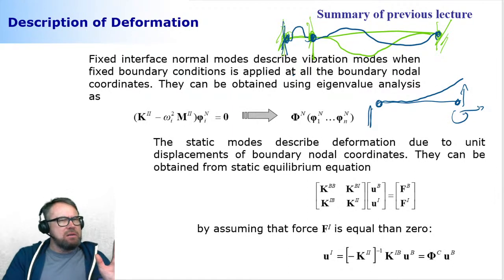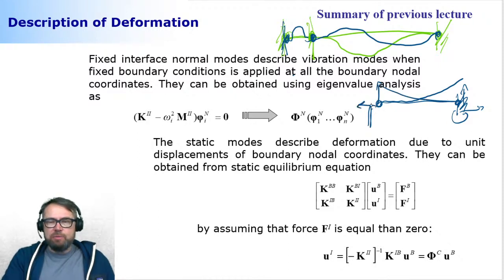So we've got a good number of different kinds of modes that are based on the unit displacement. And then you will do the same for this end here. So it will be displacement like this, there will be displacement like this, there will be rotation like that. And you will get the modes that are considered to be static correction modes. Correction modes, because they're correcting this first set of modes.